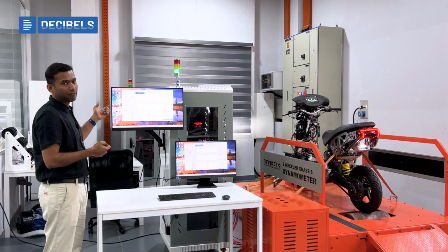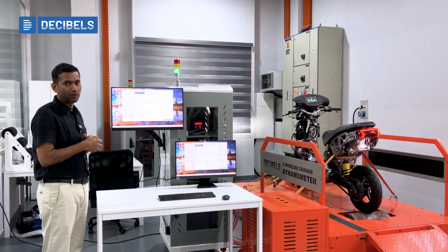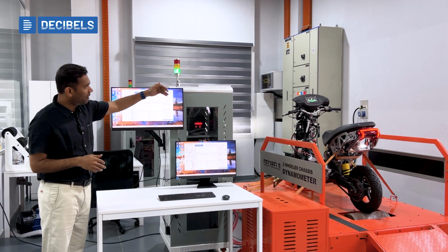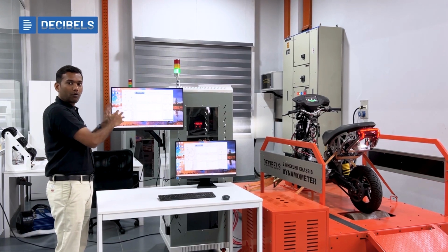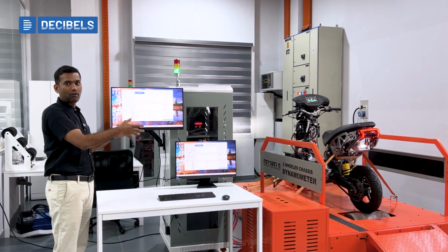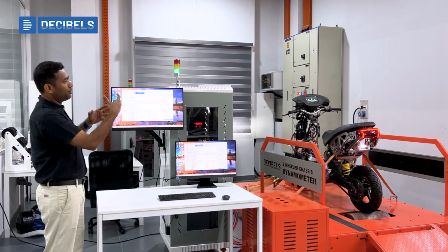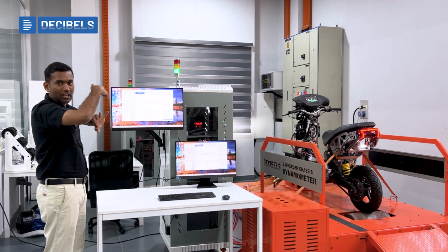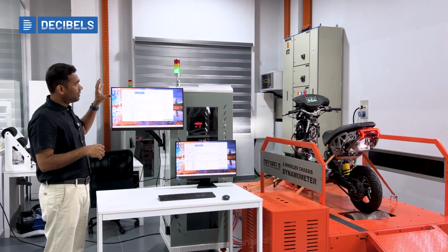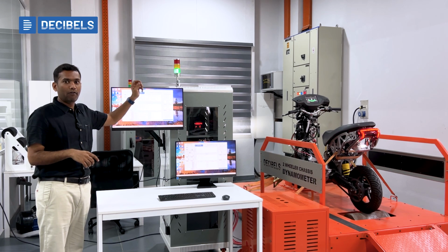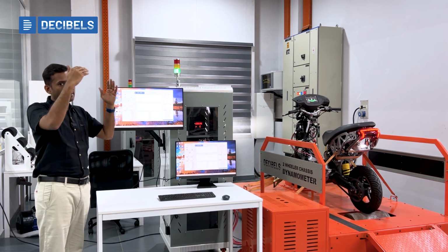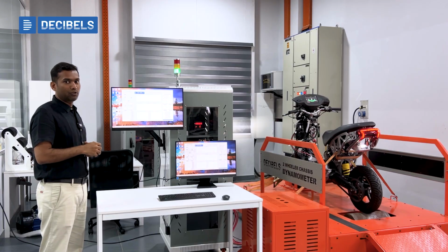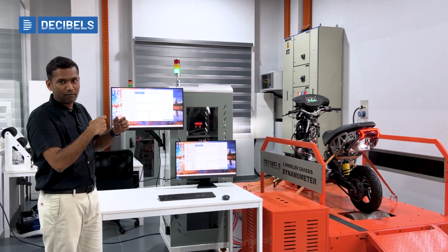That is also a part of our proprietary advanced software module, where the throttle is continuously controlled by our control software. It means if you load our IDC drive cycle, MRDC drive cycle, or any real-time drive cycle, you don't need to sit on the vehicle and keep driving it. The software will automatically take command of the throttle, and it adjusts the throttle with respect to the defined drive cycle parameters. Henceforth, we can perform closed loop controls as a part of it.